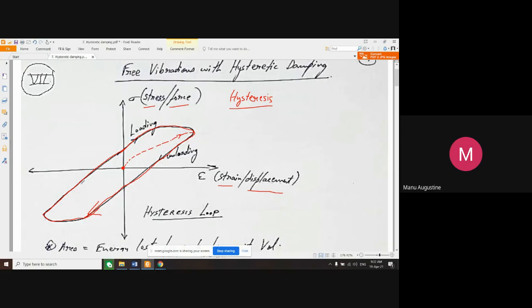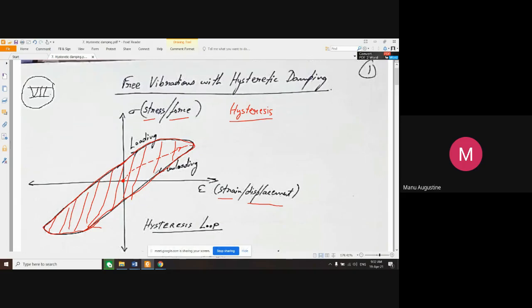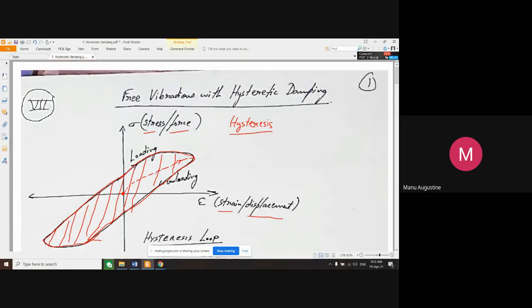Now, essentially, what a hysteresis loop represents in the case of energy loss is the energy lost per unit volume per cycle for any type of loading and unloading cycles. So, a hysteresis loop is not something specific to vibration engineering or oscillations. A hysteresis loop can occur for any type of cyclic or non-cyclic processes, but which involve loading and unloading of some elastic type of material.